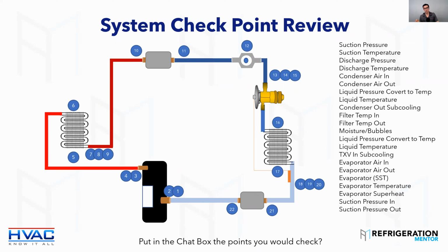There are instances where they'll say, okay, if it's a permanent installation, this much PSI drop. 1 PSI is the max, or 2 PSI, depending on it. You're going to have to look up those specs, but you shouldn't have it in there because we already talked about compression ratio, way worse than the suction line. And then always do an acid test. You got to check that oil. Got to check that oil.